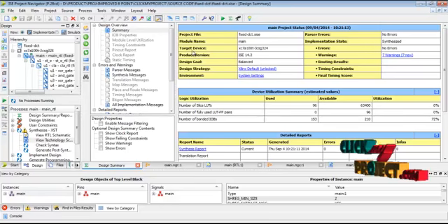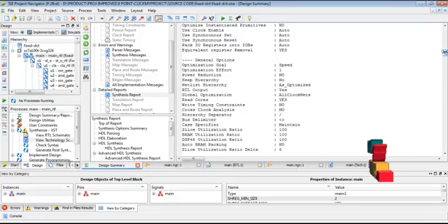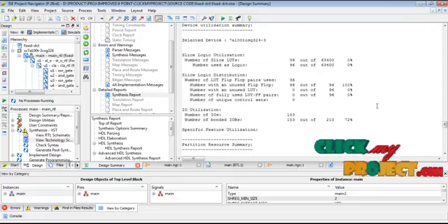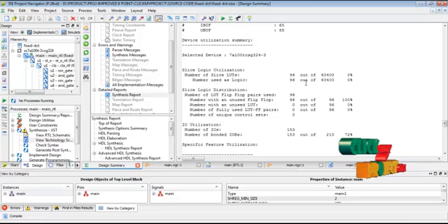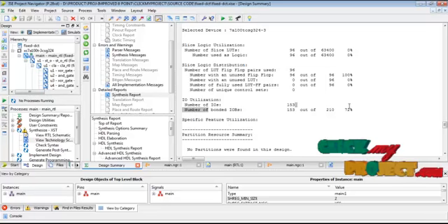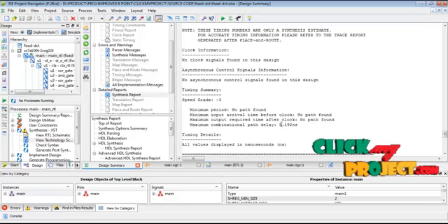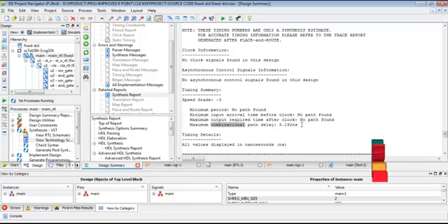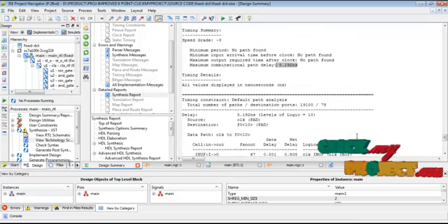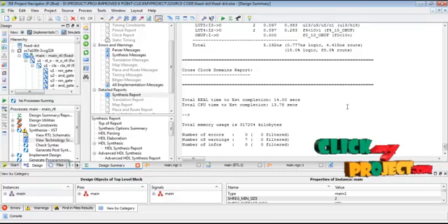Then we go to the design summary. The design summary gives the synthesis report for the required DCT architecture. The device utilization summary mainly considers the overall slices, LUTs, flip-flop pairs, and bounded input outputs. These results are mainly used for the area of the overall architecture. Then the timing summary gives the path delay time of 5.192 nanoseconds for our CSA based DCT architecture.